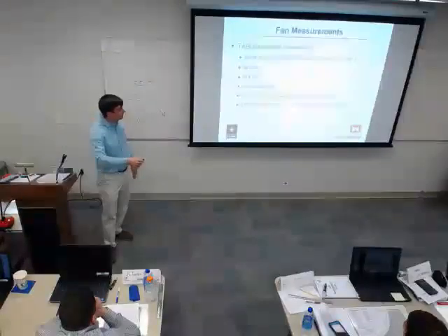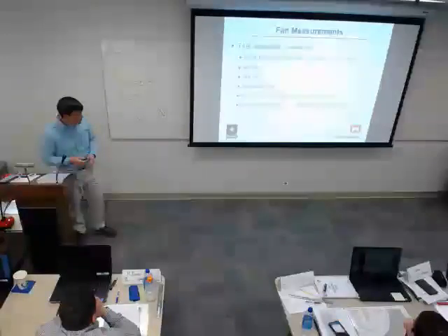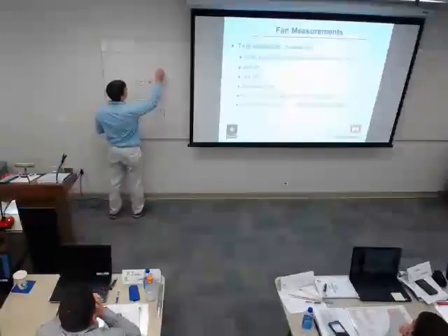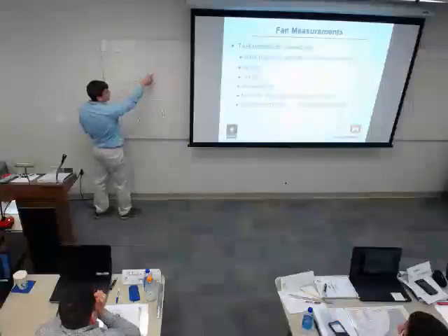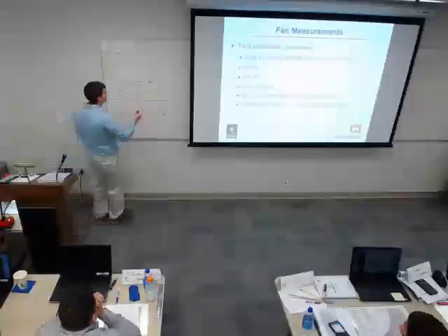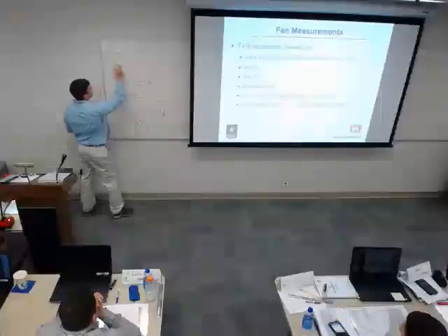And I will potentially have a difference in what my fan RPM is and what my fan motor RPM is. So if I have a direct drive fan, I may have a situation where the motor is attached directly to the fan wheel, in which case the fan shaft and the fan wheel would be spinning the same speed. But if I attach those two with a belt, I would have 2 pulleys.